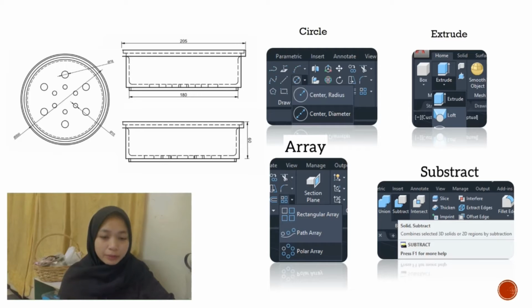Again, I make a new circle of 205mm and 200mm at the top of the object also, extrude the circle at 5mm height, and subtract these two circles, 205mm and 200mm.